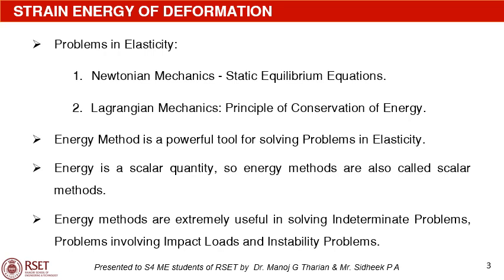Energy is a scalar quantity, so energy methods are also called scalar methods. Energy methods are based on linear elastic behavior and conservation of energy. That is, the work done by the external force is equal to the energy stored in the structure under the load. Energy methods are extremely useful in solving indeterminate problems, problems involving impact loads, and instability problems in elasticity.